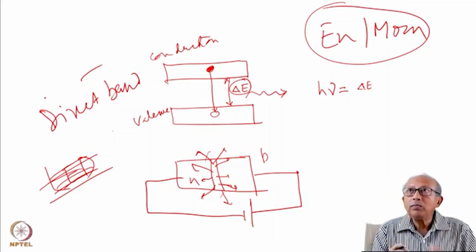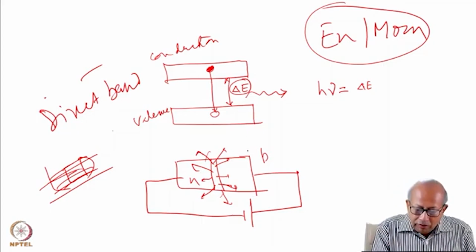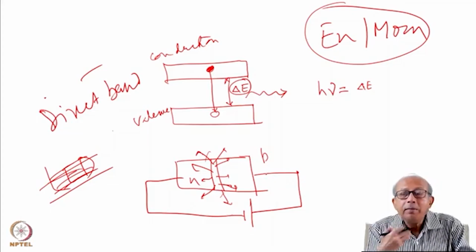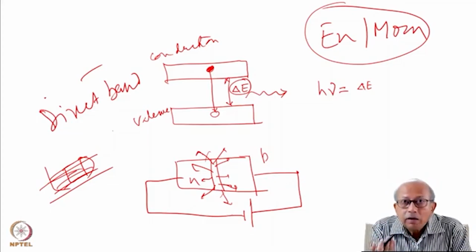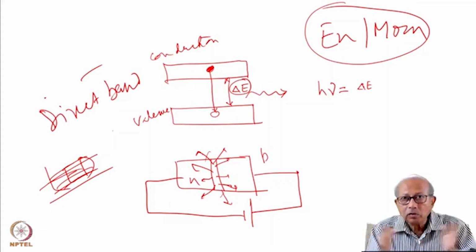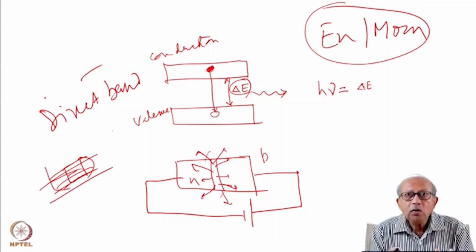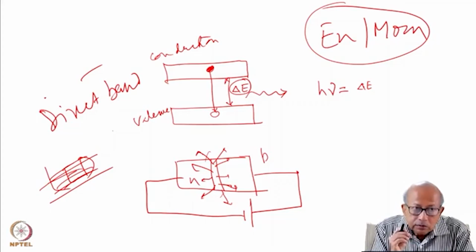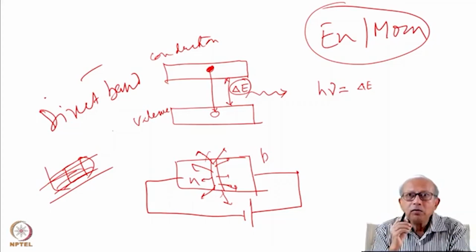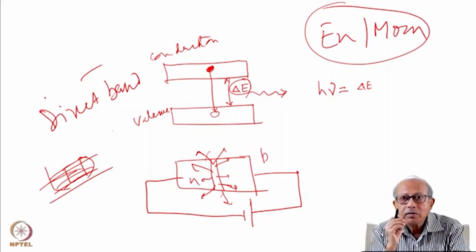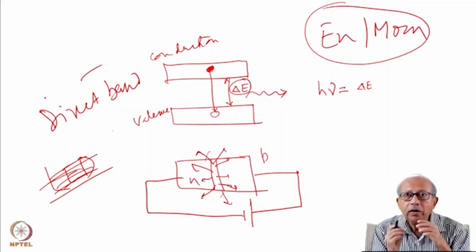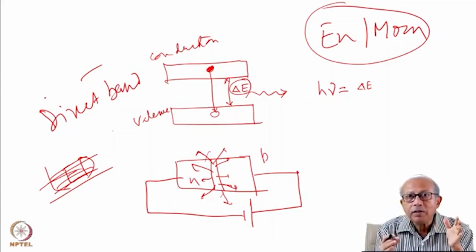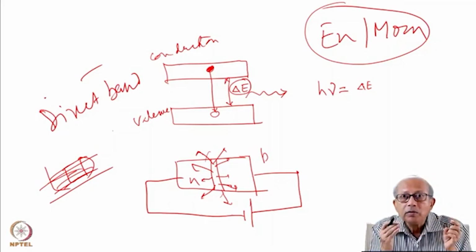Now, the important point is that if the light emitting diode can give out light spontaneously, then we know clearly that some of the photons that are emitted in a particular direction, say if we have formed a cavity, can seed the stimulated emission.